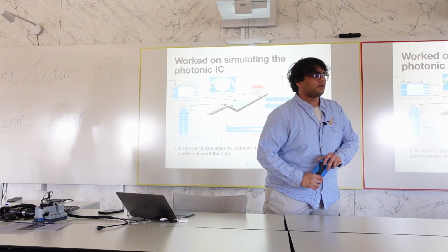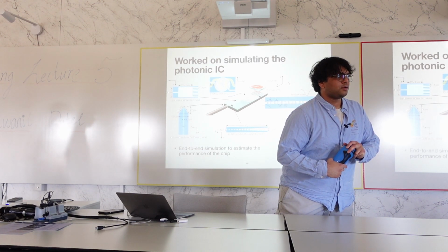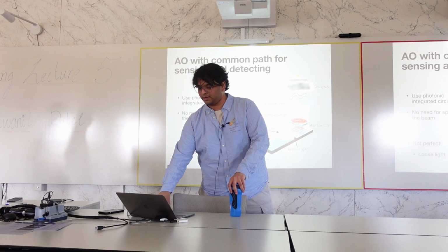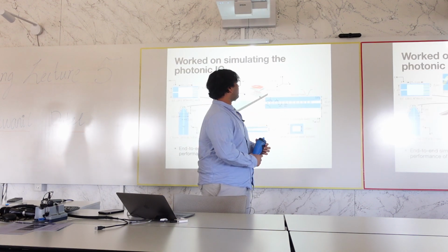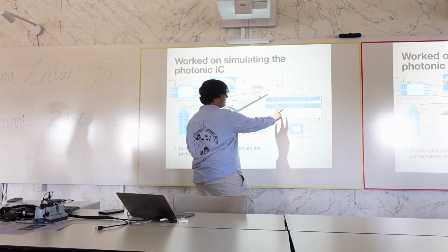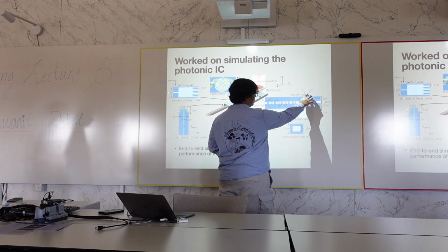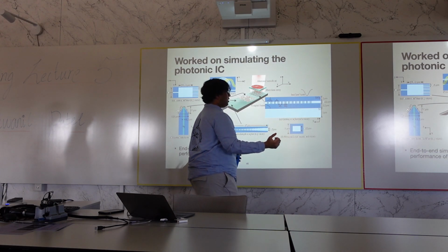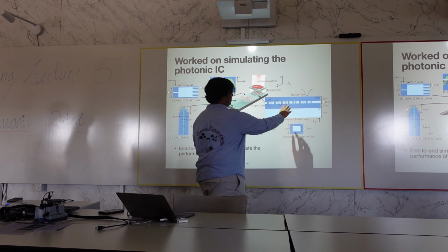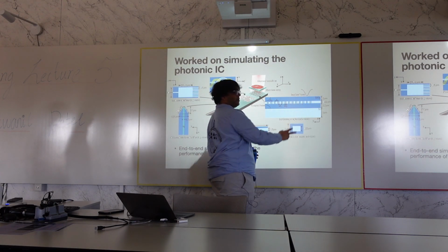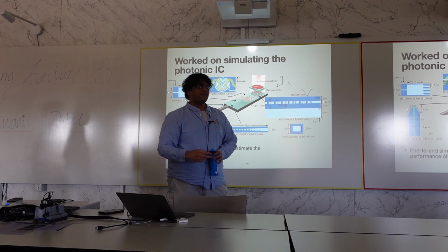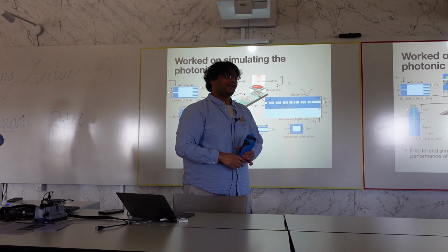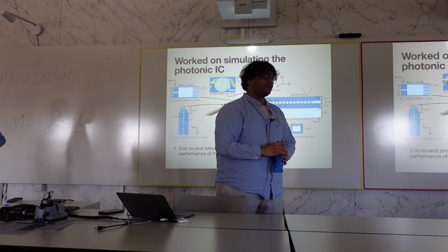Is there light energy lost when you couple the light coming from, let's say, the telescope into your chip? Yeah. So these are the grating couplers. You have your light coming in from the telescope, and it slowly couples your light into this chip, and this is the part where you lose the light. I would say the best grating couplers are like 95% in terms of efficiency.